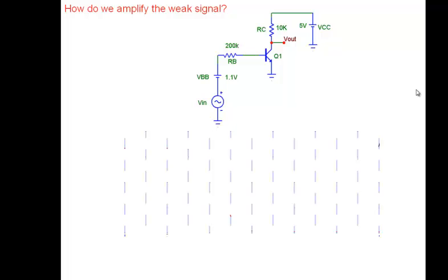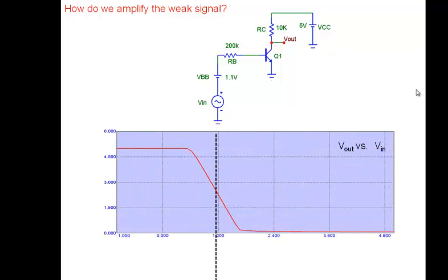Okay, now let's take the next case. It's not going to amplify in cutoff. That's why I need to bias. I need to add some voltage, and only then will it amplify. So I've added 1.1 volt. This 1.1 takes me to this operating point. This 1.1 is not the signal that I want to amplify, it's just for biasing. So I've brought my circuit into this particular state.